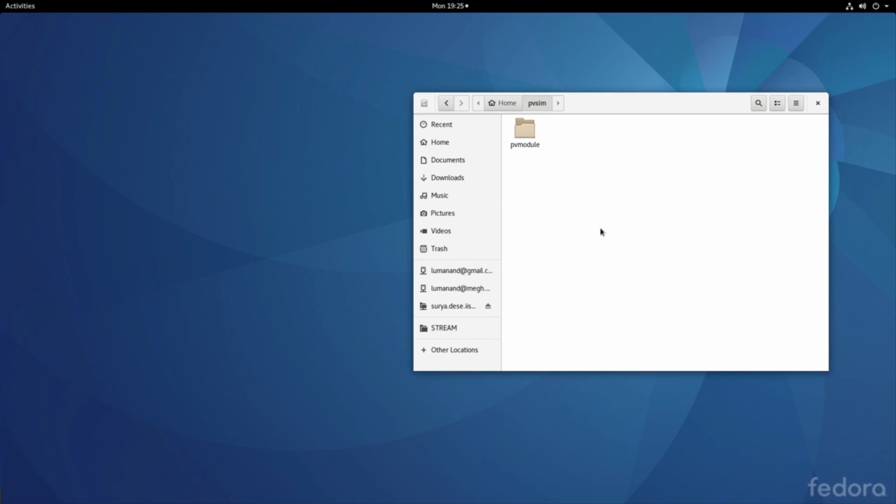Now let us try to build the subcircuit and see how we incorporate that into the SPICE schematic. I have created here a folder called PV module, and within that folder I have three files. One is the pv.cir file. You are familiar with what a CIR file is. There is a schematic file and then the pv.sub file, but I will first look at this pv.sub file where we have placed the subcircuit.